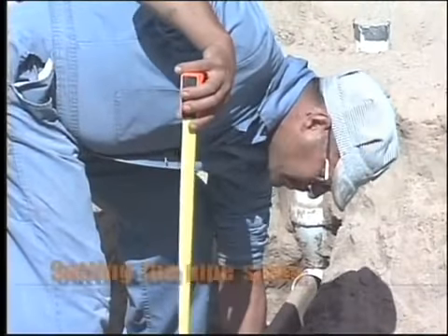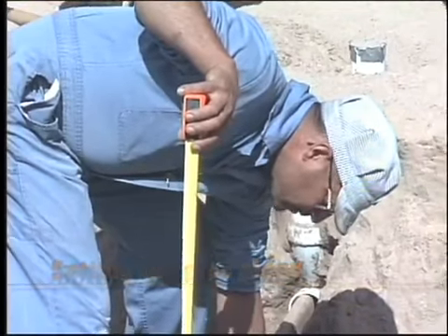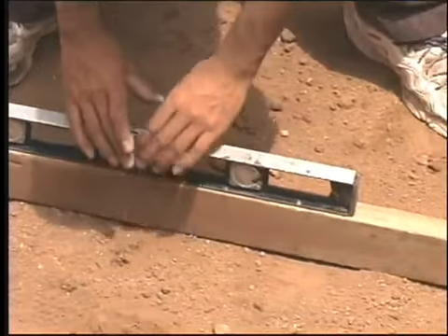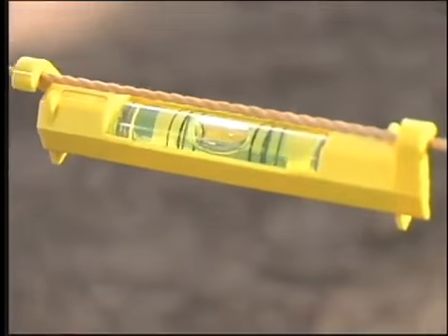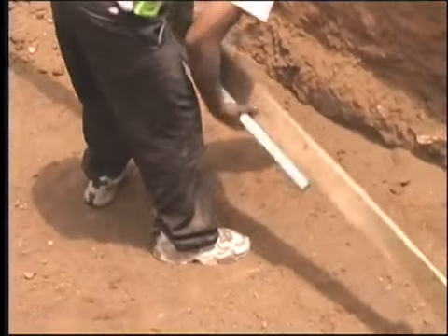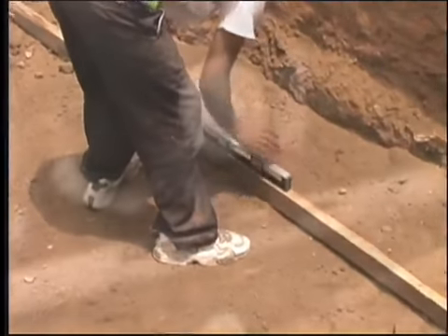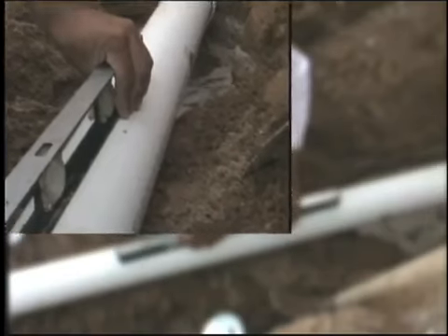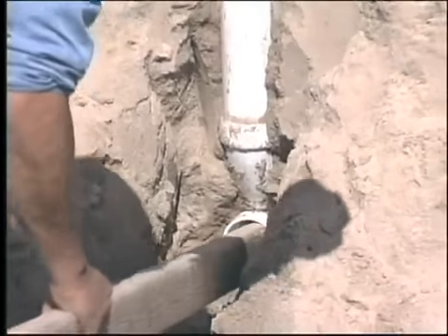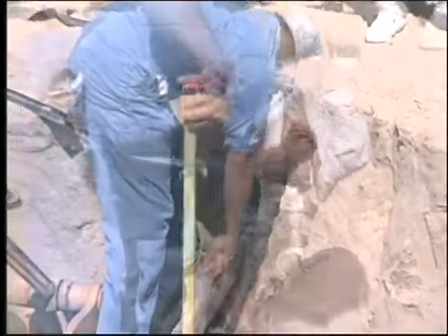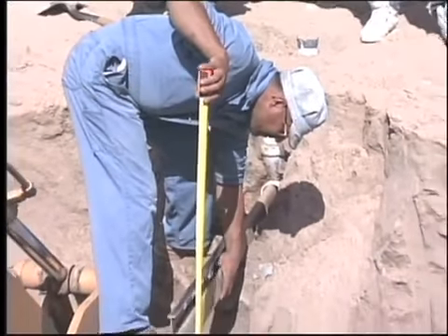The available methods for setting the pipe slope from the house to the septic tank will use one of the following: carpenter's level with 1/4 inch per foot grade mark, string level, water hose, torpedo level with laser pointer, batten boards, 2x4s. The most common technique is the carpenter's level with 1/4 inch per foot grade mark. Insert a section of 2x4 into the end of the 4-inch pipe coming from the house. Place the carpenter's level along top of the 2x4 and adjust the slope so the bubble just touches the line closest to the pipe.